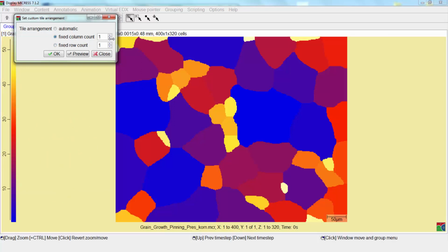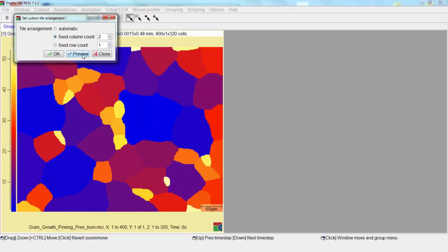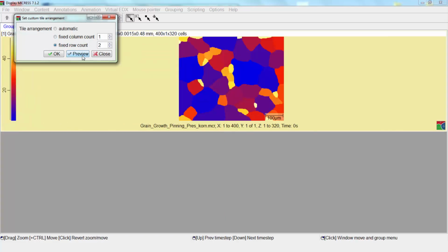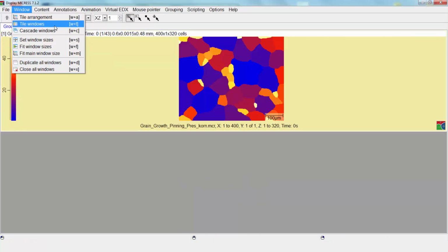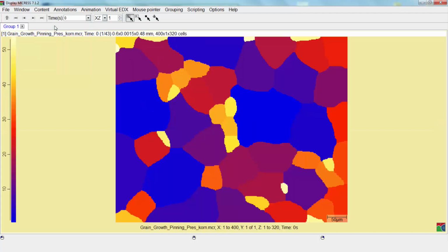This means that if the columns are set as 2, one dataset is presented in a way that a second dataset could fit into a second column next to it. The opposite is happening when fixing the rows as 2. Then there would be sufficient space for a second row under the other dataset. Arranging windows by the Tile Windows tool affects the layout of the result files. The datasets are organized in a way that the available space is fully utilized and consequently the background is avoided.